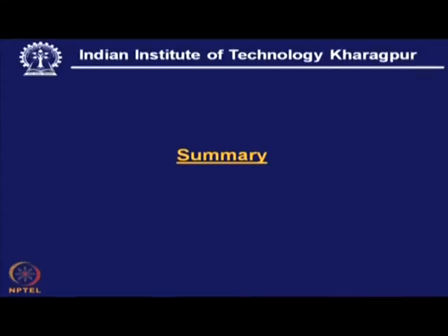What we can see now in the summary is that in the vacuum system we have two options, low vacuum or high vacuum, but for most CVD processes it is a low vacuum, and that can be well handled by mechanical pumps like the roots pump, vane pump and water ring pump. At the very beginning the vane pump is used for pre-evacuation of the system, and when the CVD is on, it is the water ring pump that is operational, and in the process we can also use a roots pump for increasing the throughput of the system.